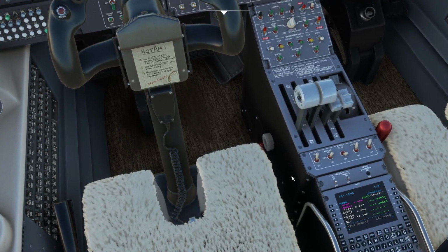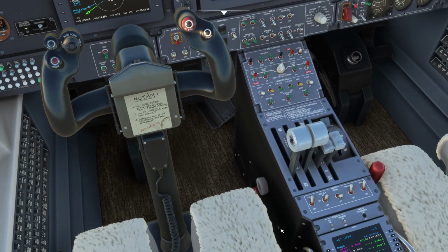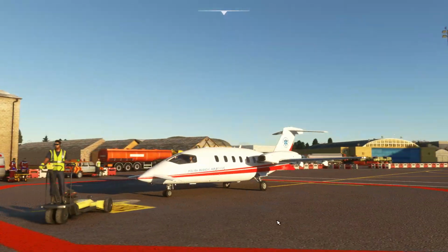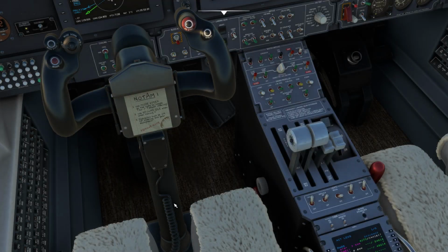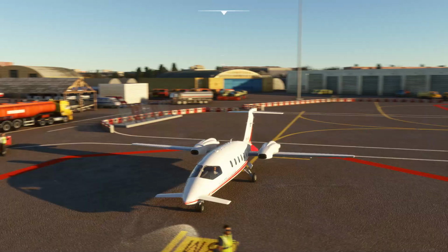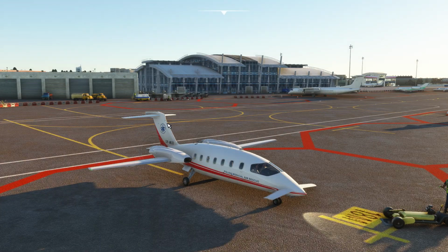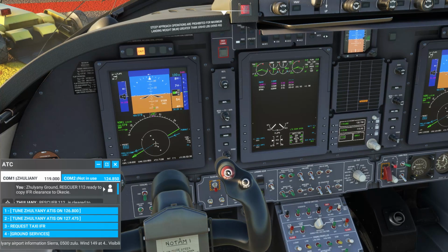Taxi. So generally, taxi lights are here. If you pull it up one notch, it's taxi. You can hear it coming down. So taxi light is here. It moves out of the aircraft's nose, which is cool. And recognition, we want to be recognizable from distance. Recognition light is this one here on the tail. It illuminates the fuselage on top. Landing, recognition, and we can request the taxi.